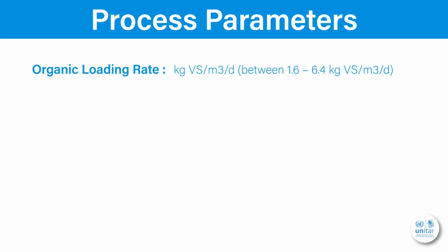Ideally, a digester shall be fed as regularly as possible. The OLR can indicate if we are over or under feeding the digester, in comparison to the design value. Overfeeding would have an overloading of the digester as consequence, which might cause the digestion process to fail. In worst cases, the digester needs to be restarted if it can't remediate.